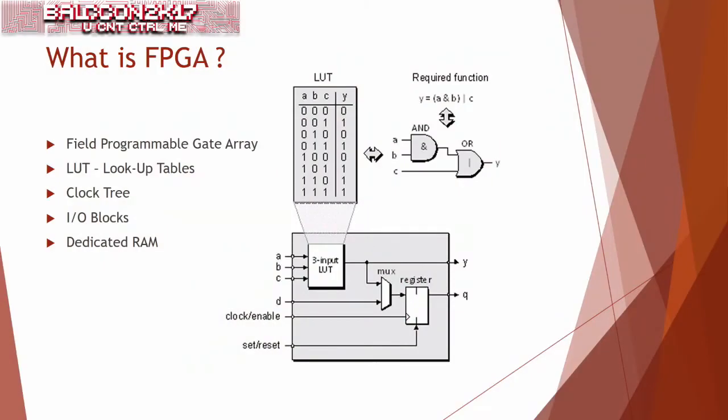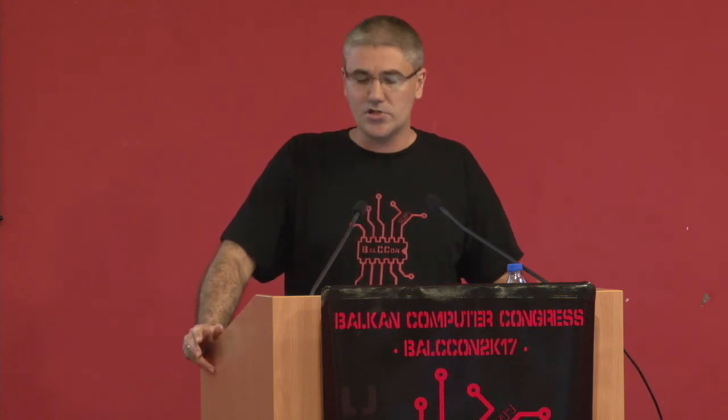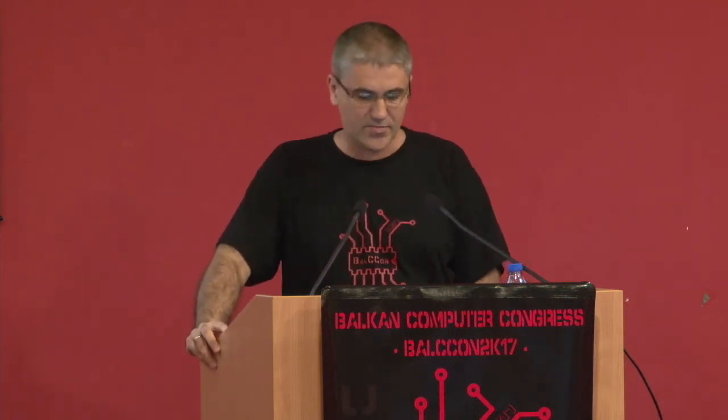Some of the FPGAs, most of them nowadays, have dedicated RAM because in some designs you need a RAM section, and you don't need that much combinational logic. You just need a lot of D flip-flops and address buses and so on, and you have that implemented inside. So your tools can recognize that and use that part instead of these flip-flops.